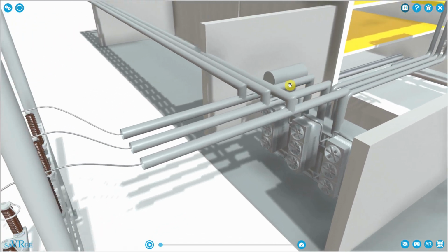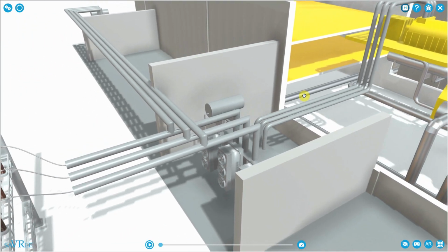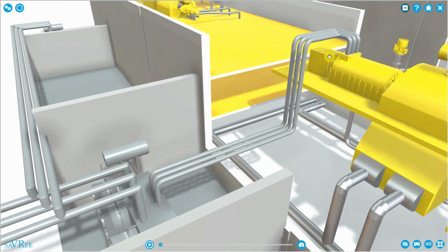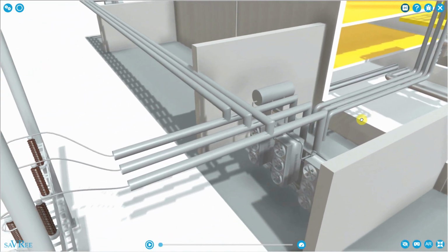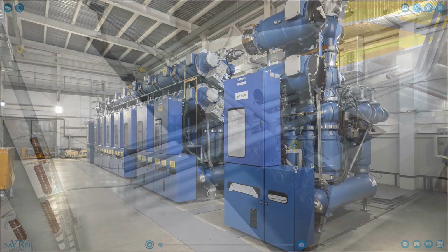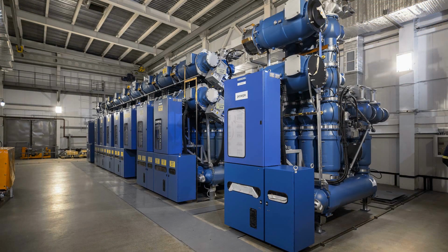What's not shown here that you definitely will see within any power station is the electrical switchgear. Typically you'll have switchgear between the generator and the transformer, and then you'll have switchgear between the transformer and the open air switchyard. Switchgear are similar to circuit breakers. When you install switchgear, you're attempting to protect any of the equipment that's installed upstream or downstream of it.